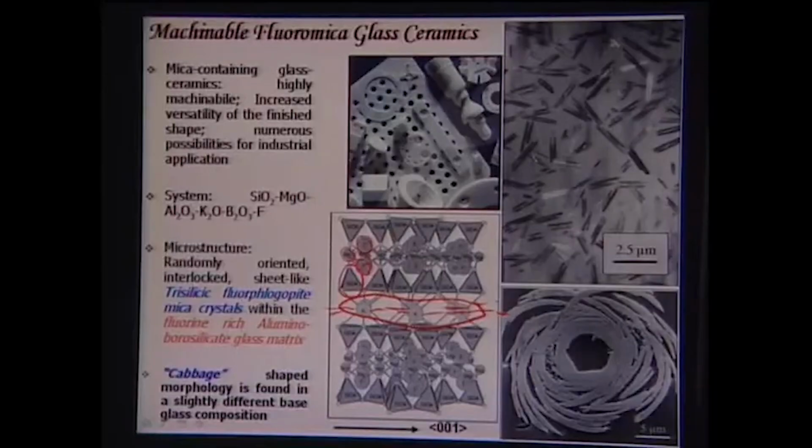When you synthesize these materials, the first and primary step for glass ceramic production is to get the base glass composition. Now, how is this base glass obtained? Applying the conventional ceramic processing routes, one has to mix these different precursor powders in a desired ratio, then it has to be molten, and during the melting process all these oxides are mixed with each other, and this mixed oxide melt is cast, and typically the casting is done in a platinum crucible.